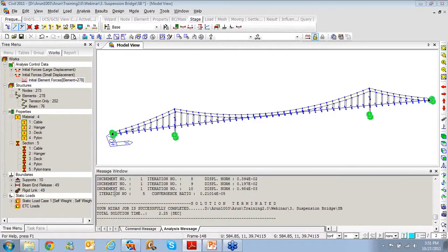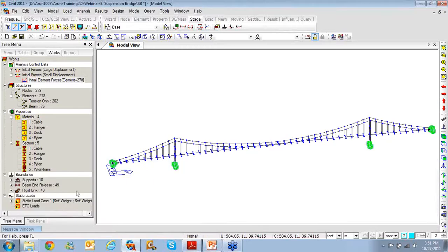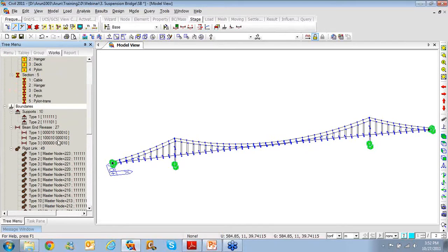and we'll do that in this manner. So we know the type 1 is 00010, and that means at ith end, at ith node my is released, so I don't want this set of links, so I'll delete them. And not the link, sorry, the beam and releases, and then I'll delete the other one also, and I'll modify the type 1 and type 2 now.